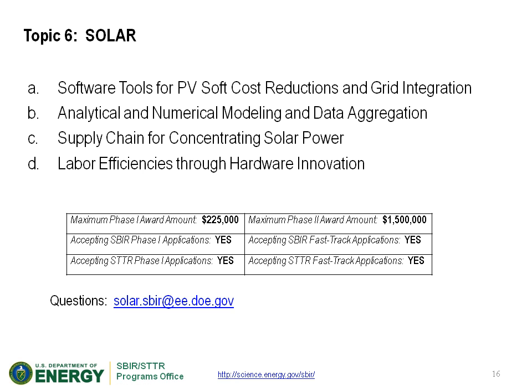We also believe there's a role for IT in facilitating cost-effective grid integration of PV systems, specifically to aggregate, visualize, analyze, and control PV at the distribution feeder, substation, and sub-transmission level in real time, to synchronize and manage integrated PV resources at the distribution level, and to expedite the utility PV interconnection technical screening process. Some means to achieve these ends could include open source and enterprise tools, bulk transmission, and dynamic distribution engineering analysis software, and others as identified in the topic description.